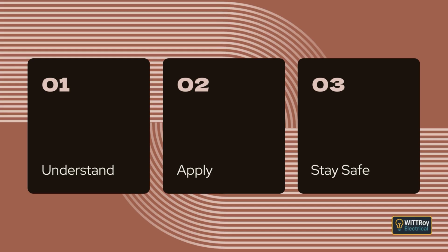Clause 2.3.3.4 Identification. This clause explains that every main switch must be clearly marked. It should have permanent wording saying main switch, and it must stand out from other switches so that anyone, even in an emergency, can find it quickly. If there are multiple main switches, each one must indicate which installation or which supply it controls. If operating the main switch also switches an alternative supply, such as a generator, this must be clearly shown. The whole purpose is to avoid confusion and allow fast, confident operation.